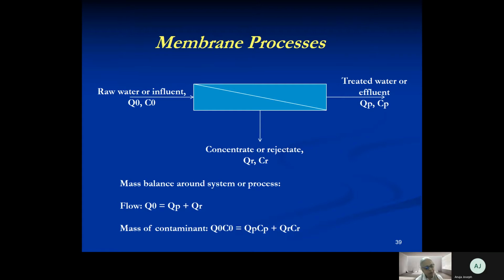Another thing for all of you to remember is that, especially in RO systems, you generally have a cartridge, and the cartridge has different types of filters. You may have these noodle type filters. Imagine your noodle as a hollow fiber. The entire cartridge is filled with hundreds of these noodle-like hollow fibers.